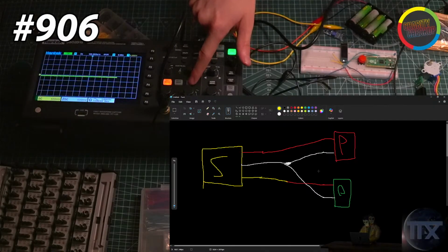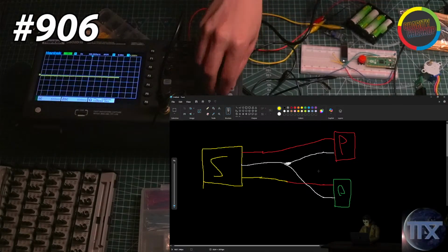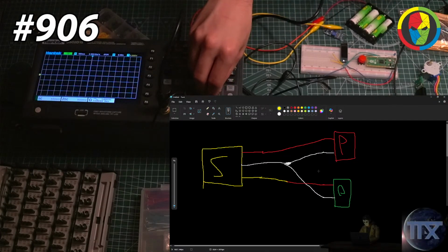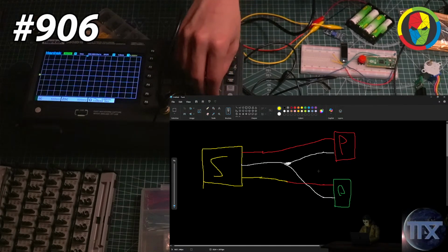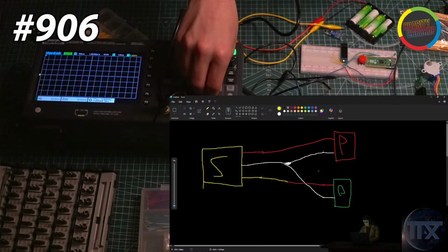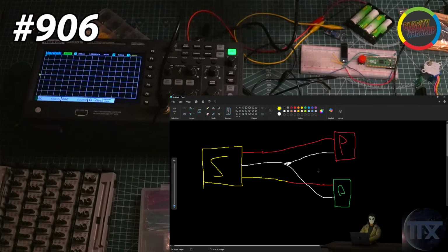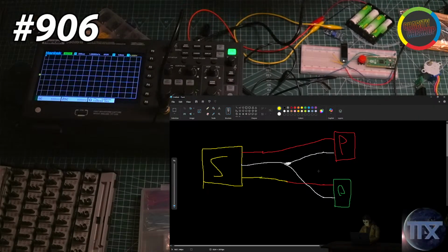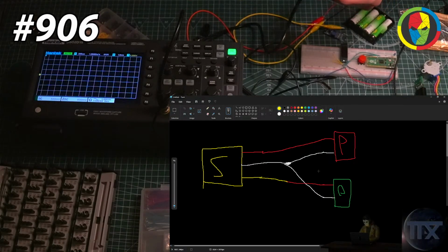Oh, that's the menu. Yeah, zoom in the time domain because it's going to mess with it. It doesn't have much memory. So first, just zoom in on the time domain because it's having to display a lot of information and it might be capping, kind of like an internal processor. Okay, so now it's in 200 microseconds. Okay, yeah, just let it sit there until it actually draws on the screen. And you're in auto, so click the auto button a couple of times. Hold on. Where is it? It seems it's right by the green button that's lit.